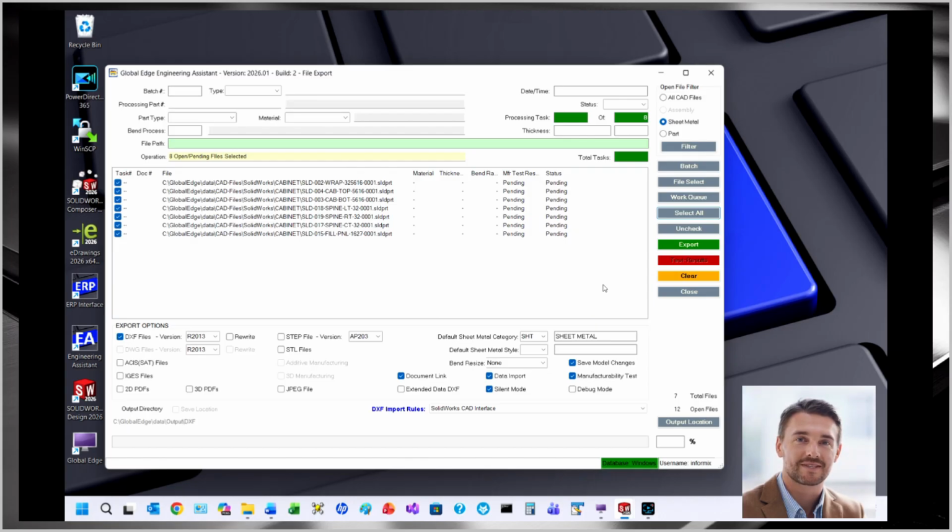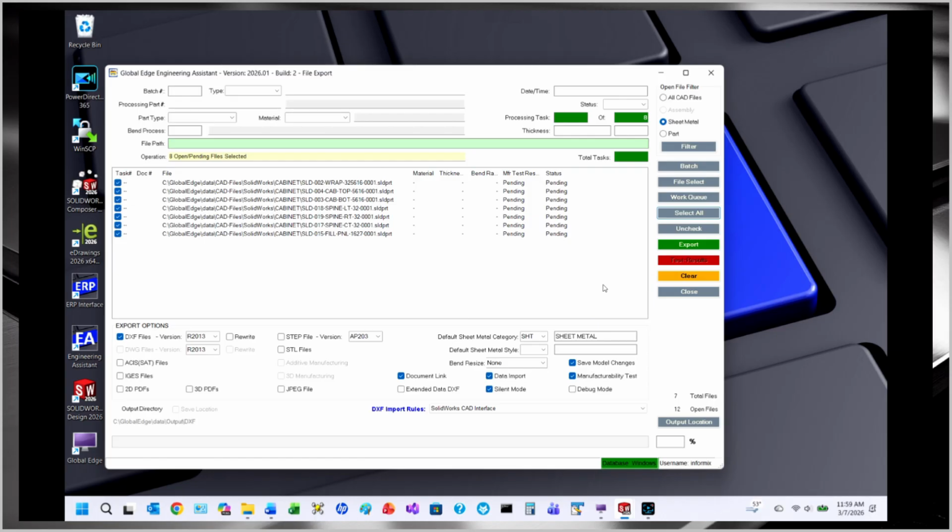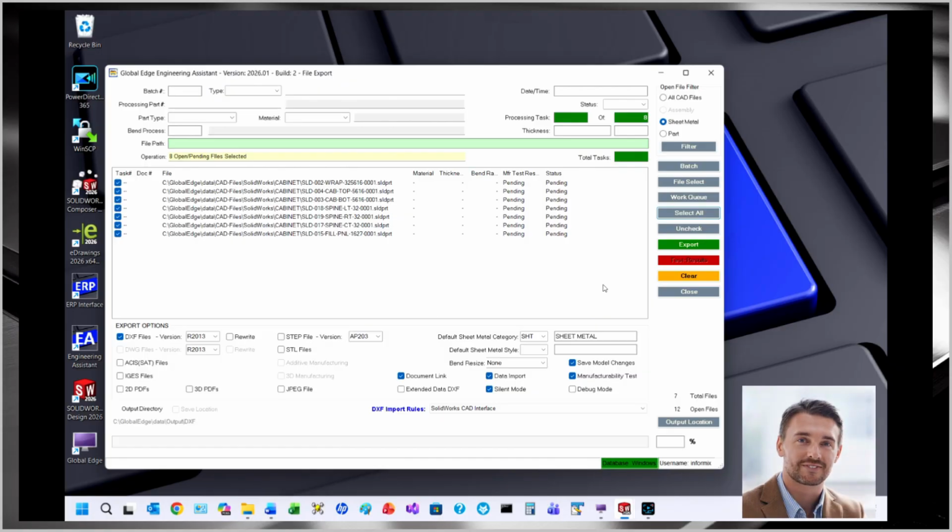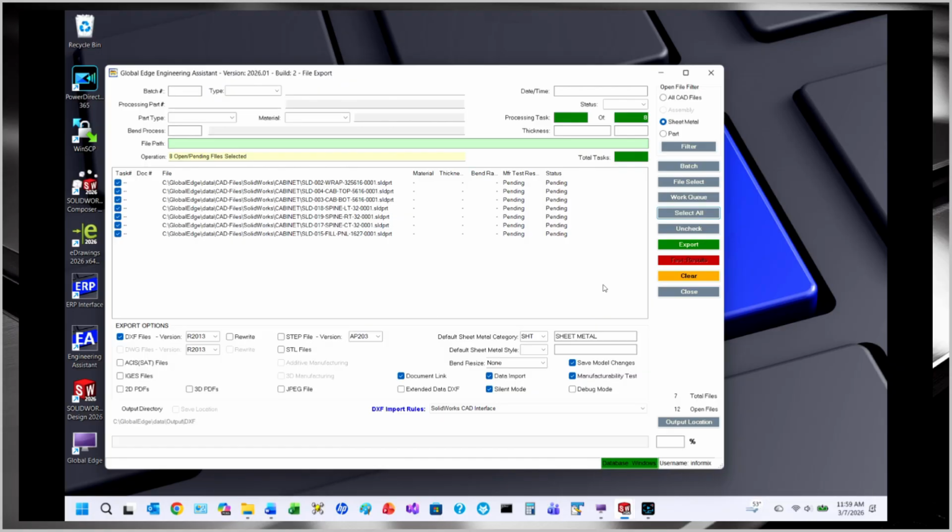This includes the automated incorporation of extended data into the DXF flat files that can be directly imported into CAM bending software. This process eliminates the manual programming of sheet metal part files for press brakes, robotic folders, and panel benders. Select the Export button to start the processing of the selected sheet metal part with the output options that were selected below.